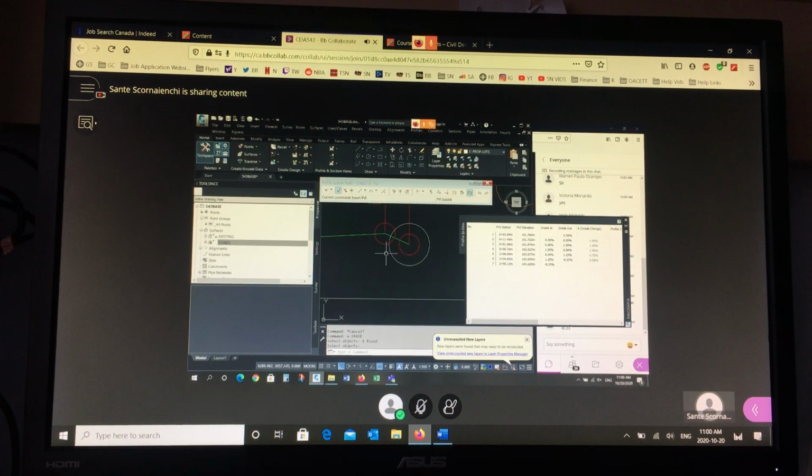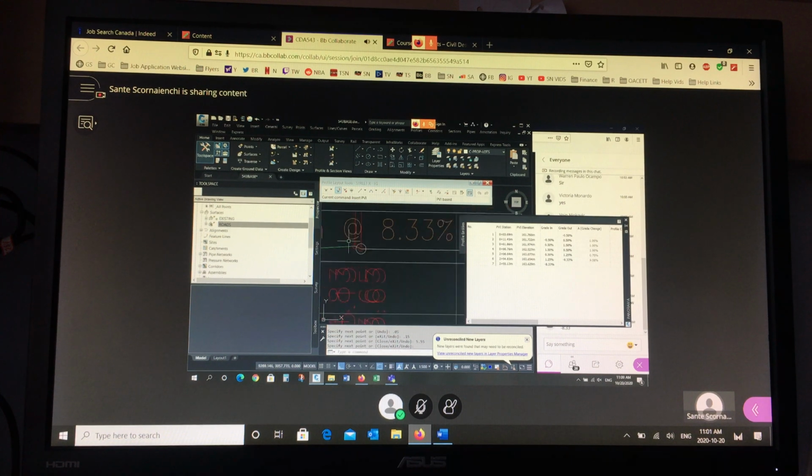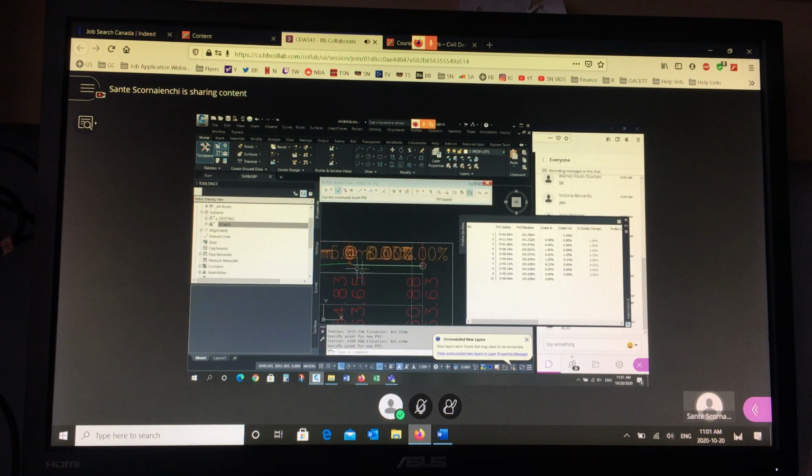If you want to draw the entire boulevard, you could do this. I'm going to draw a line at the end. 0.05 is the next width. Think about the cross section. 0.15, the top flat of curve, and then I can put in 5.55, the actual boulevard width. And if I do that, now I have all the station values. I can add more PVIs. There's going to be one right here, one here, and one at the end. And then I can change the slope.